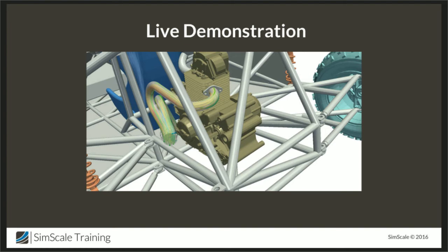What these recirculation zones or blockages do is that they reduce the performance of the manifold and in turn the performance of the engine itself. So this can be analyzed with CFD, and you can implement a CFD simulation in the design process in this way.